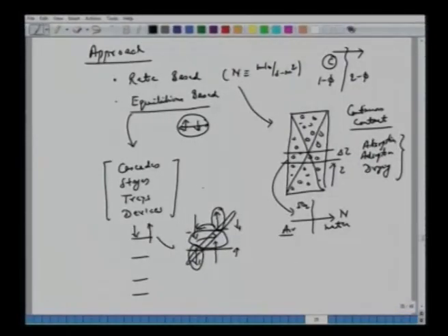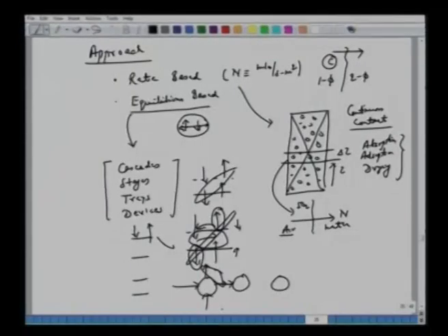After this, the streams go to the second tray. There you have the same situation. Here you bring in contact other liquid, they spend some time here, then they leave in equilibrium. So it's an equilibrium-wise approach. You can also think of certain vessels in which one phase is brought in contact with the second phase. The two leaving streams are in equilibrium. They have spent some time. You bring to the second stage, stage 2, after stage 1, again in contact with some different solvent. Again they get mixed and there they leave.